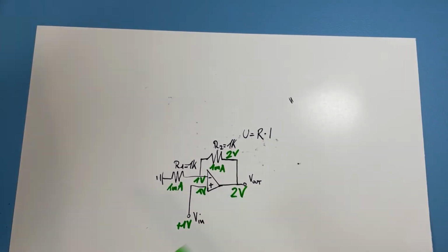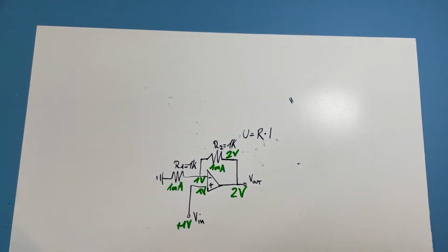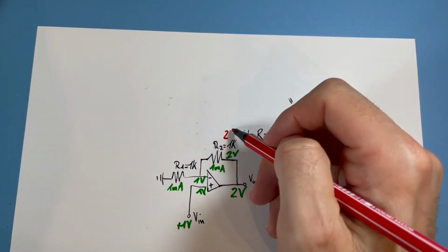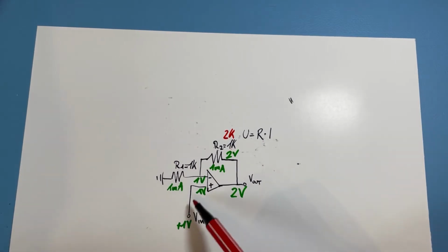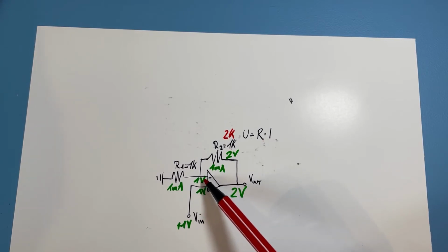And then you can do another thing. We can move to that resistor here, R2. Let's say we have another case, and we draw it in red. The case is that this is a 2K resistor here. Again, same situation. We put 1 volt in. 1 volt is here at the plus terminal. Then the OpAmp tries to get that also to 1 volt at the negative terminal. It does it from itself. That's its job, so to say, to get the terminals to the same potential.